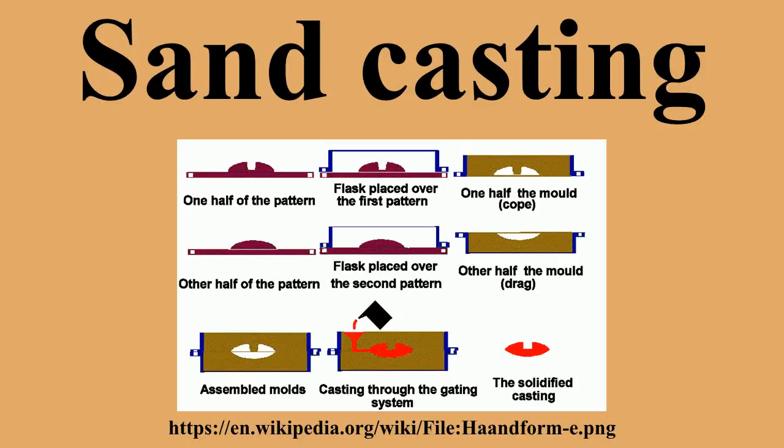Most foundries do not have the very expensive equipment to remove the burned-out clay and substitute new clay, so instead, those that pour iron typically work with silica sand that is inexpensive compared to the other sands. As the clay is burned out, newly mixed sand is added and some of the old sand is discarded or recycled into other uses.